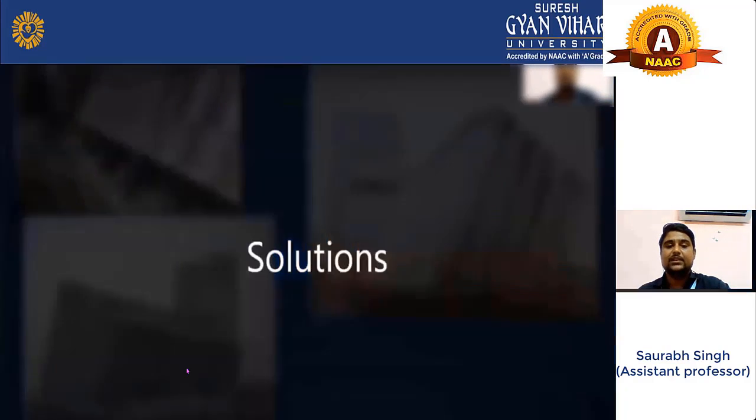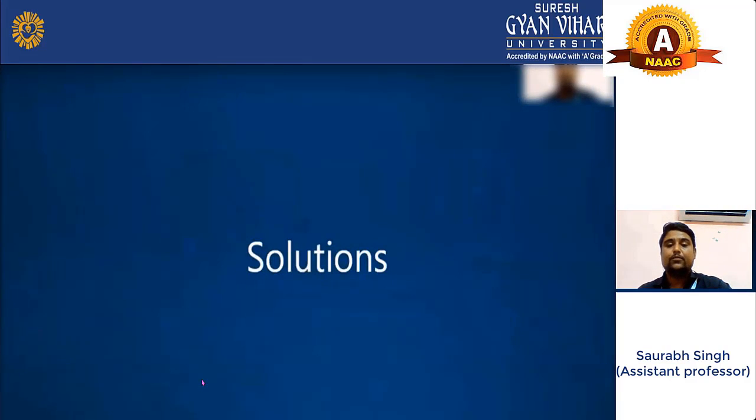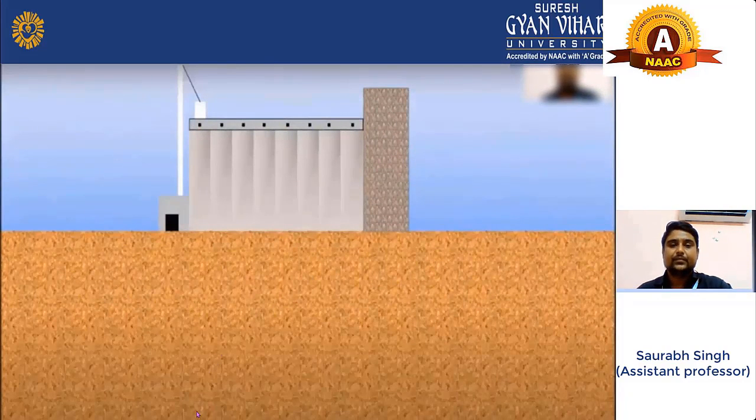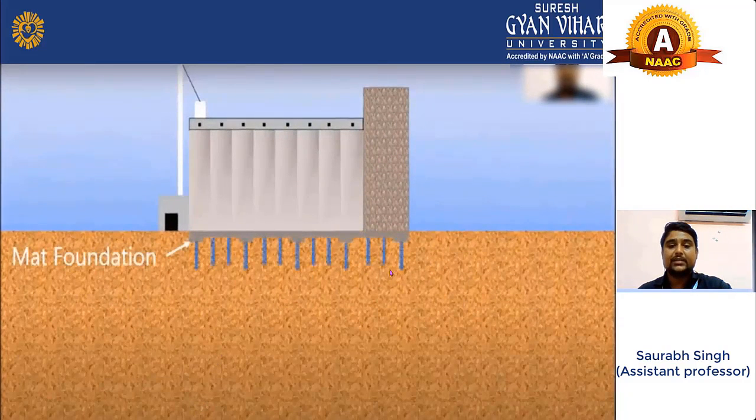This is very important to know what is the bearing capacity of soil where you are going to build your structure and what is the solution. As you can see in this animation video here, you can also make a mat foundation here. What will happen if area is increased? Your intensity of load will be decreased.